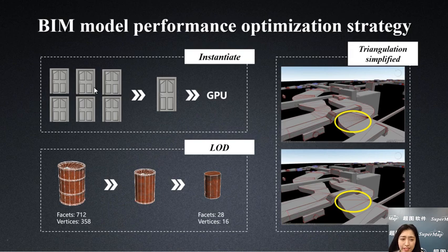And as shown in this figure below, there are a large number of the same door objects in the house. So using the instancing functions and rendering technology, only one object is saved and drawn, which reduces the pressure on the graphics card and the memory, and improves the performance of the 3D scenes. Okay, that's instancing.